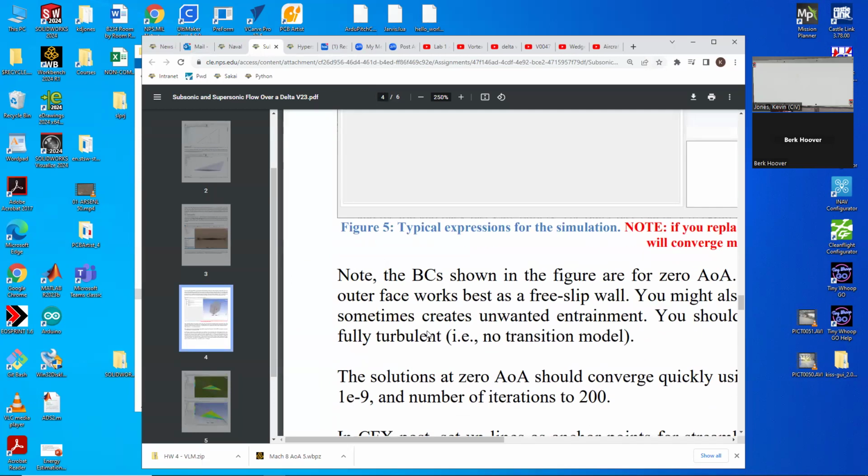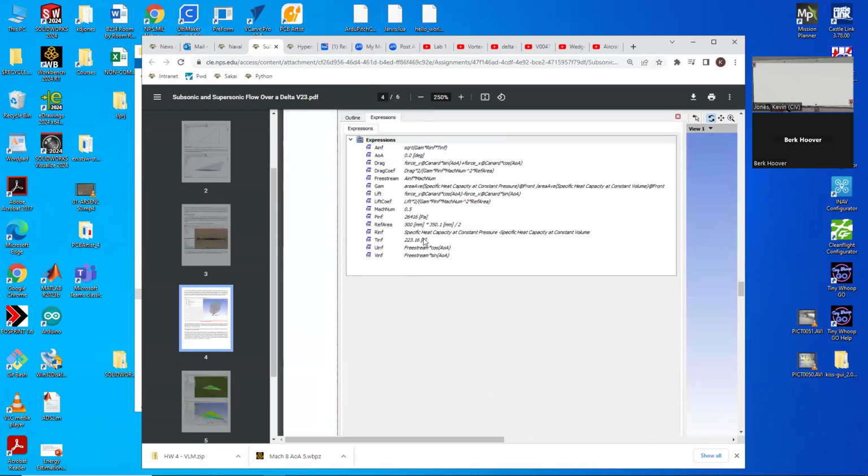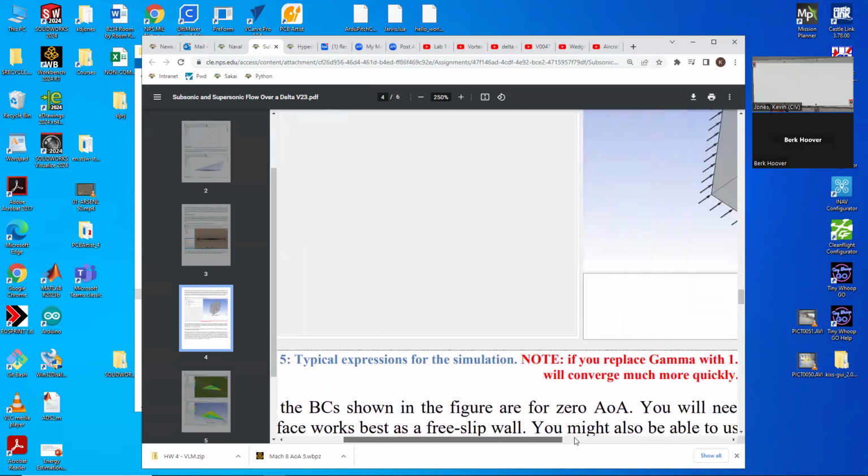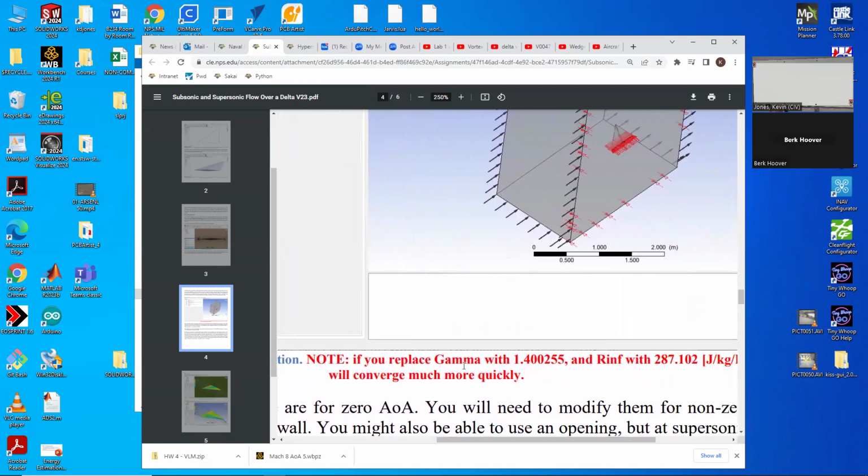If you look at the RMS behavior, these actually do cause some grief in the supersonic case. So if I were you, I would swap them out for hard numbers, and then the convergence would be a little bit quicker. They all converge pretty fast.